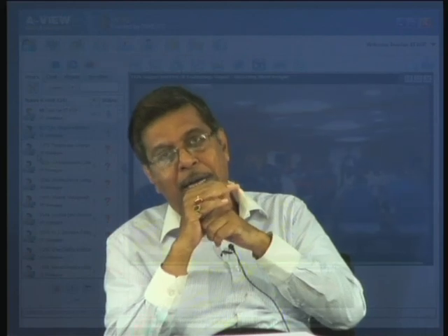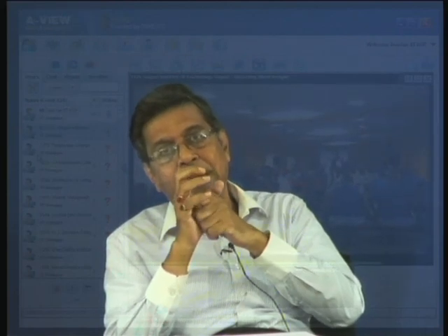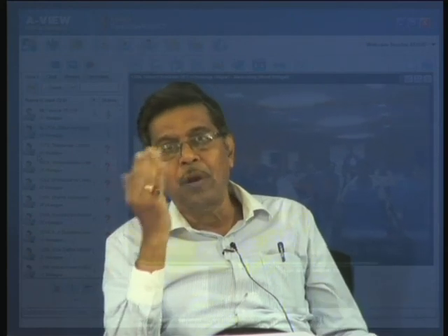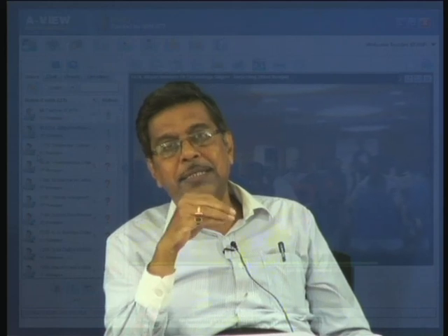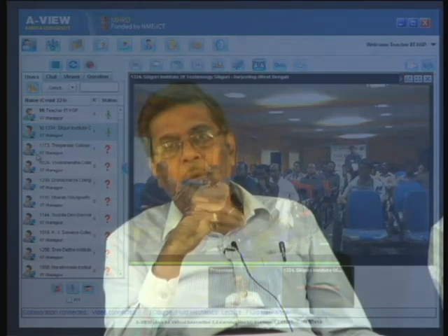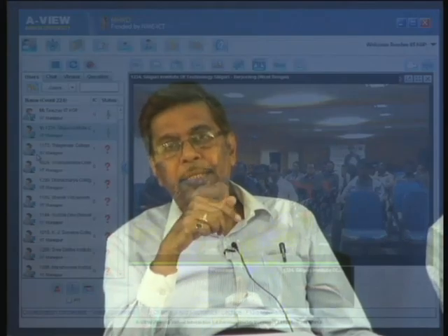You have understood. So for an impulse turbine, for example in a Pelton wheel, what happens in the nozzle is the expansion of the liquid. Expansion means the pressure at the inlet to the nozzle is fully utilized, so that the discharge pressure is atmospheric pressure. And in a Pelton wheel, the jet comes at atmospheric pressure and it strikes the blades of the Pelton wheel one by one as it rotates.